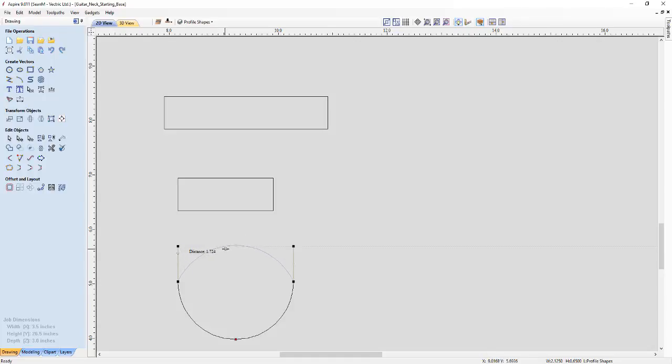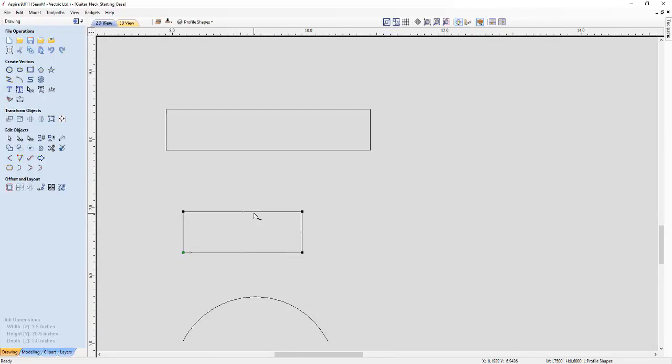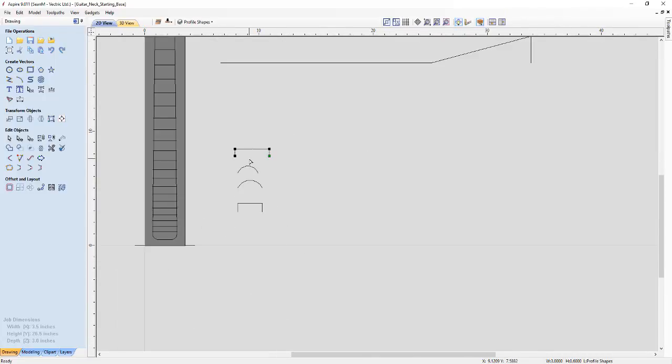And then when we join in the middle, you'll see that we will get a notification where we've got basically a cross of both of the guides, like so, and just simply let go of the left mouse. Then all we need to do is delete each side of the profile. And again, we just need to do this again for the one above. So just going to delete the top span, change this to an arc, drag the control node, match it up, and you'll see it can be done nice and quick, just like that. And again, the top one, because this is just going to be a flat shape for the headstock, which all we need to do is simply delete the actual bottom span. So press D on the keyboard once we've hovered that over.